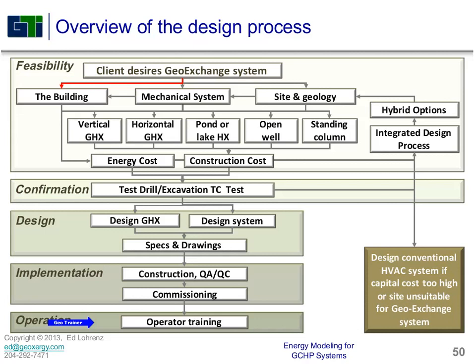I had one question about using the ground loop design software to use a coaxial heat exchanger. Dan, do you have any comments on that? We're planning on adding that functionality into an upcoming release of the software. But what I've seen is they typically reduce the ground loop lengths approximately equivalently to a W bend. So if you're trying to get by with a best guesstimation, the W bend is one approach. Ed, what do you think?